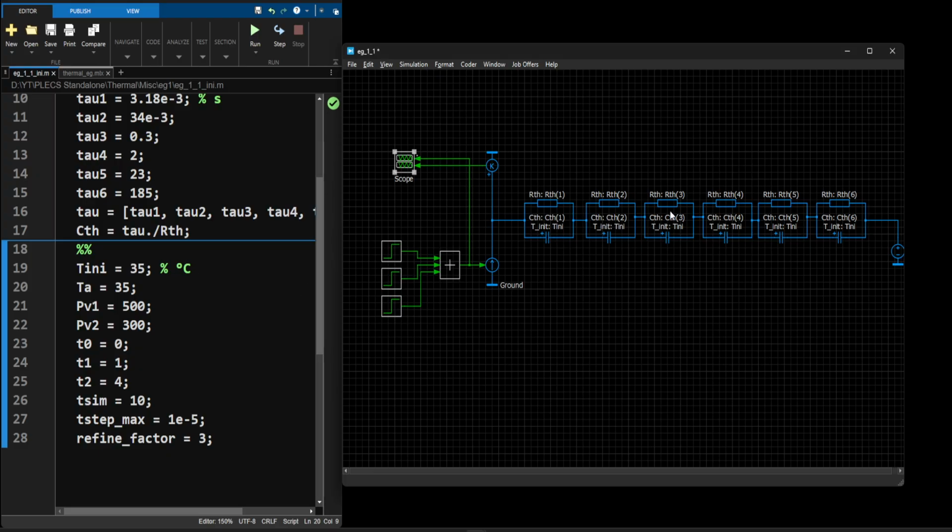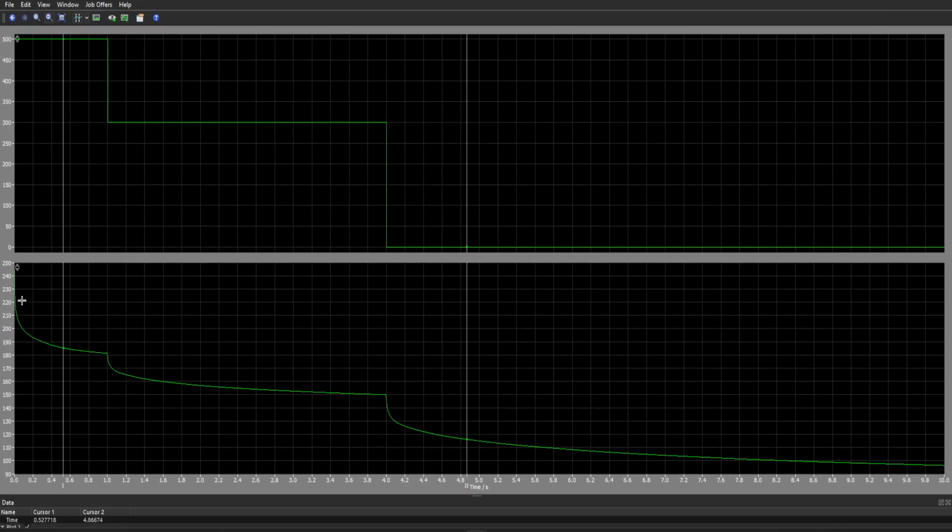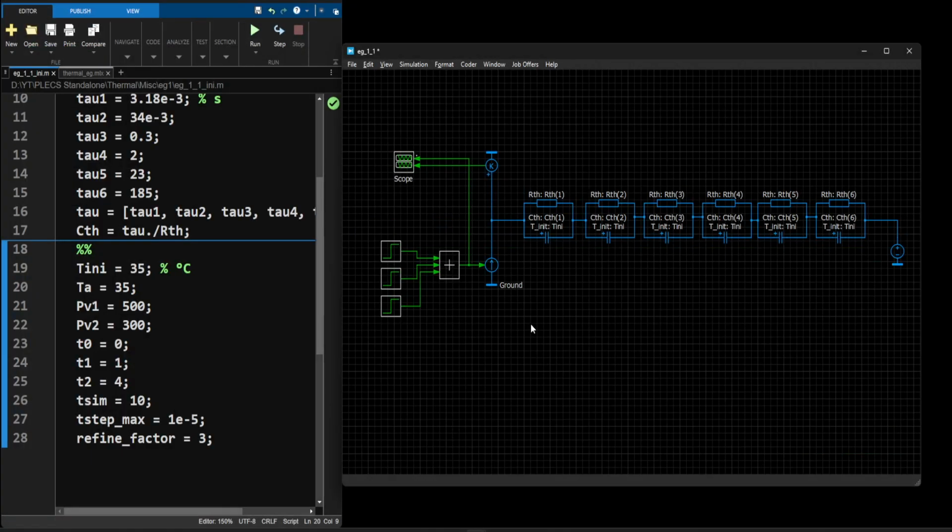They're in serial connection. So T1, T2, T3 for all of the thyristor pairs, they're serially connected. And if you add 35 times 6 plus 35 as ambient temperature, you should have 245 at the beginning, which is not realistic. The temperature should rise following that exponential curve from the ambient temperature. So the problem is to be solved by setting the initial temperature of each RC pair in the Foster model to 0.